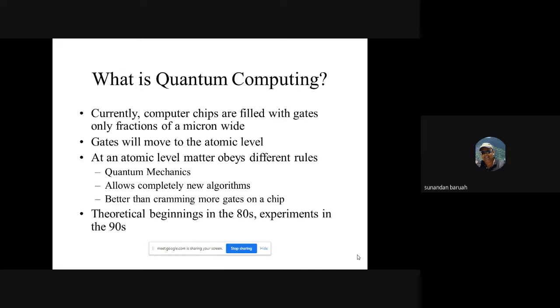We are not moving away from Moore's law. You all know about Moore's law, right? Roughly, you can say that the transistors on a particular integrated circuit or surface area of silicon will double almost every 1.5 years. That means today I have 1 million, after 1.5 years I'll have 2 million transistors on the same area of the chip. And we have not yet gone for multi-level active components, believe me. We talk about multi-level chips, but when you talk about the active components, that means the transistors, they're still on one single level. The other levels are used for interconnecting.